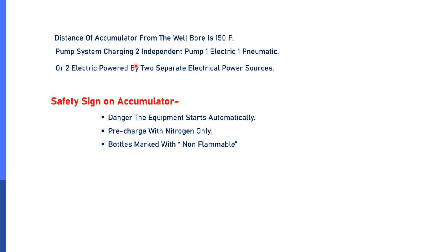The pump system charging has 2 independent pumps, 1 electrical and 1 pneumatic, or it might be two electric pumps powered by 2 separate electrical power sources. Why? Because if one fails, the other will be workable and will be used.